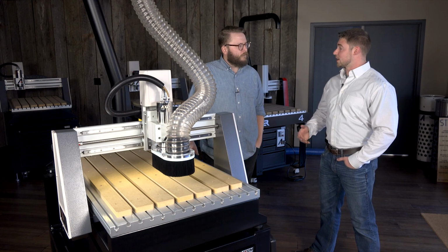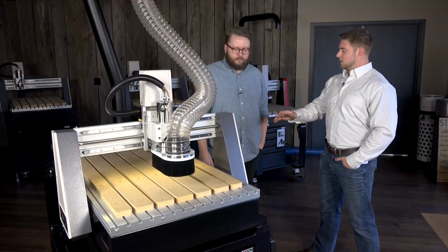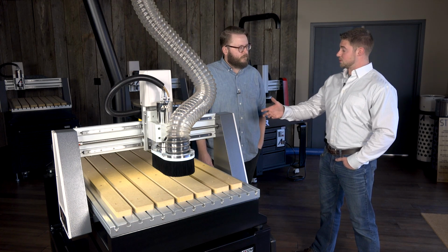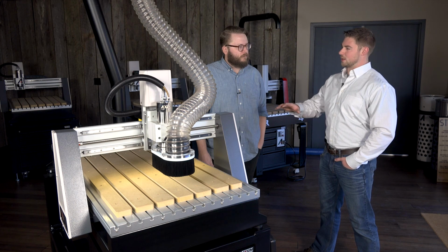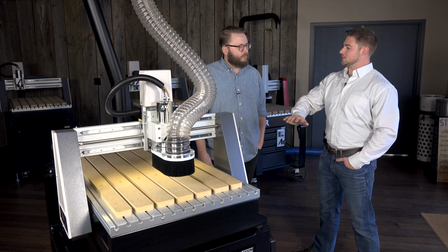So a spoil board is just a sacrificial table, but you can have an inconsistent thickness across the tabletop. So our goal is to take a few thousandths of an inch off the surface of the table to make sure that it's consistent no matter where you are. So that Z distance, the bit to the table, is the same.